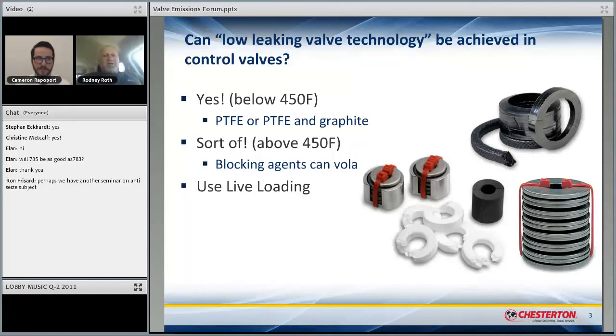The standards that it applies to currently are 600 and 602, where it's actually written in and required. And when API 623 and 603 are republished, it'll be required in those. Those valves are already in the standard to be tested. 623 is for globe valves. 603 is for thin wall body alloy valves. 600 is what is considered the cast steel valve standard, and 602 is the compact port valve standard.